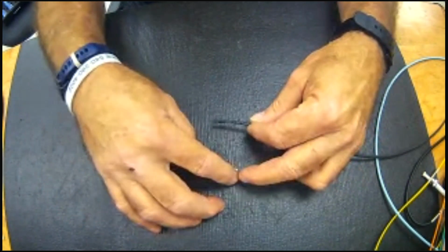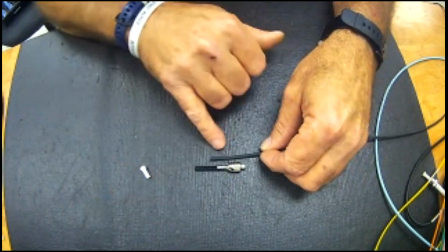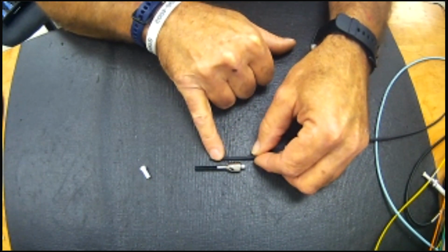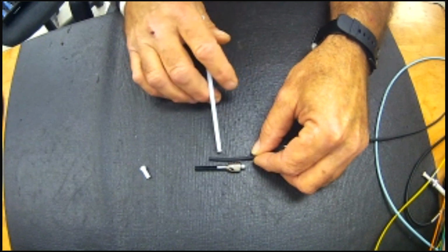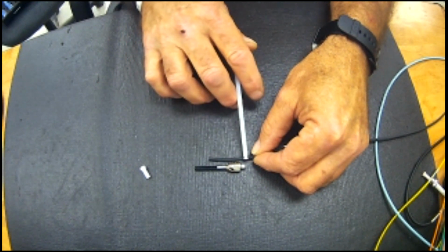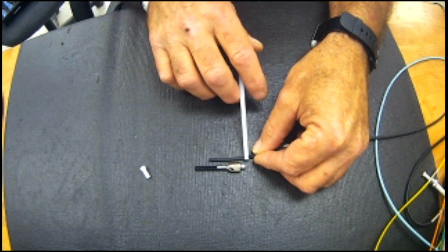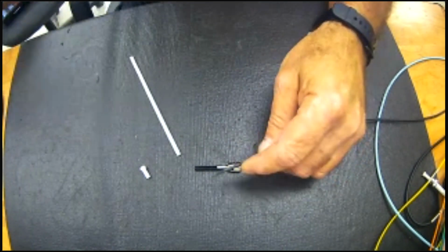Now you can look up the manufacturer and write out or use a ruler to specify dimensions of the strip, but I'm going to tell you, if you just learn to eyeball it, you'll be fine. It is a 3-stage strip, just like a coaxial BNC. You would first remove the jacket material to expose the glass and the yarn, and it would have to be longer than the entire length of the connector plus some. So I'm going to do that first.